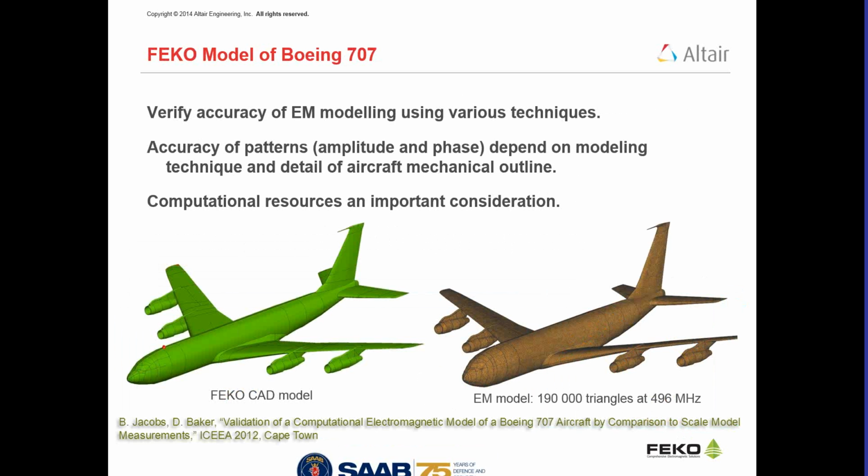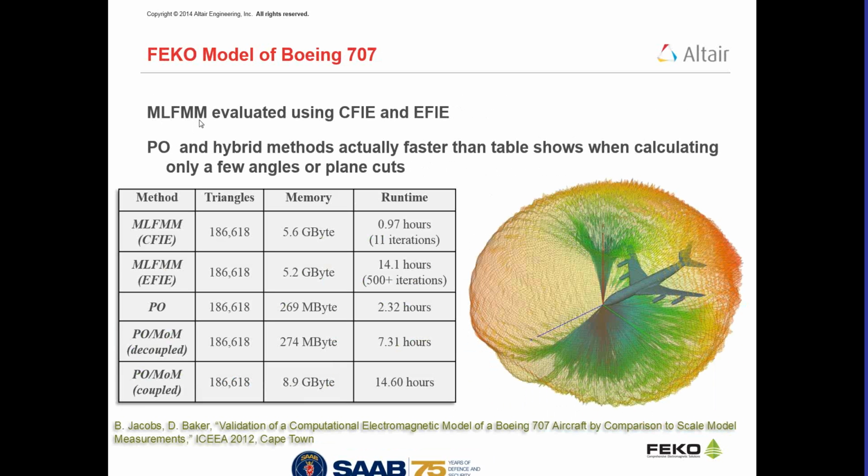It's important to make sure that the computation resources are also within reach for these types of problems. So they used MLFMM. In FEKO, we offer MLFMM in two flavors. One is CFIE, Combined Field Integral Equation, and the other is EFIE, Electric Field Integral Equation. EFIE is pretty good for open surfaces. That means you have openings like windows and things like that, or flat plates and other kinds of structures.